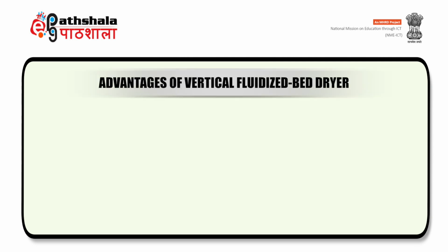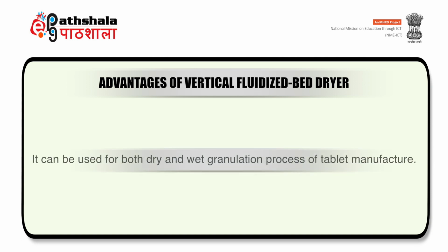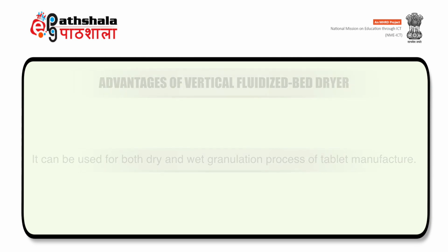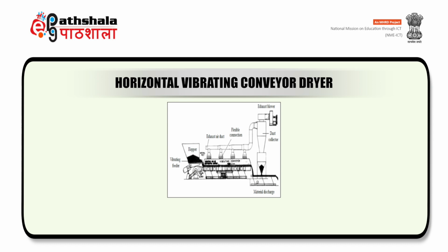Advantages of the vertical fluidized bed dryer. It has short drying time, it provides excellent mixing action, no hot spots are produced, higher drying temperatures can be used, and it can be used for both dry and wet granulation processes of tablet manufacture. Now we will discuss the horizontal vibrating conveyor dryer as shown on the screen.